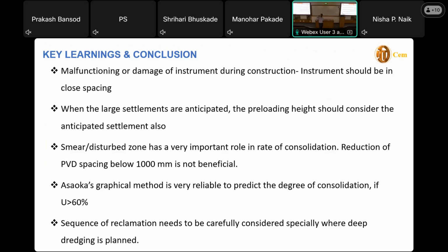So the 10 will become 8. So what are you left with? You only have 1 meter above plus 7, because you have to have plus 7, otherwise you have to have 55. So you should anticipate those settlements, calculate them, and top it up initially. So instead of 10, we put 12, so that after settlement you have 10, which is your desire.